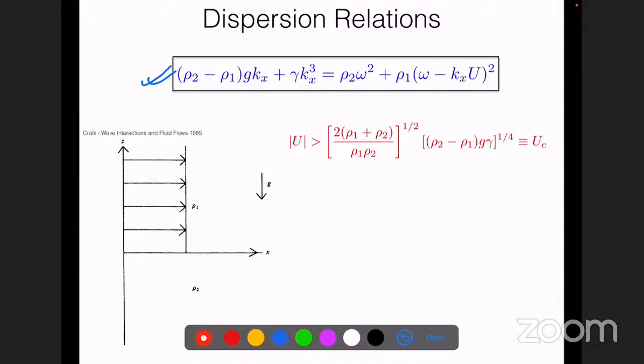So the gravitational restoring force, when you perturb the interface, gives rise to the surface gravity waves. When there was no flow, when you perturb the interface, there is a restoring mechanism due to gravity which leads to these waves propagating. So this restoring mechanism of gravity can actually prevent the instability from occurring if the wave number is too small. Similarly, if the wave number is too large, then you cannot have an instability because surface tension is going to be the guy which will champion over everyone.